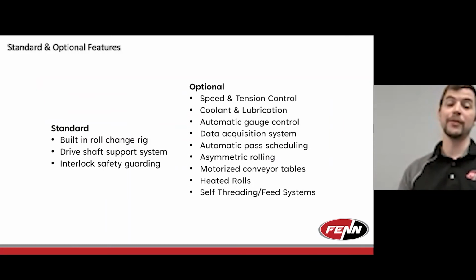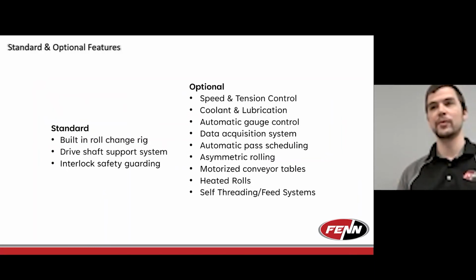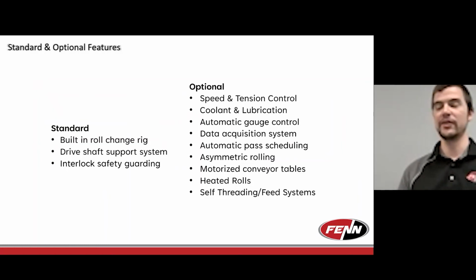So the majority of the time you're doing maintenance on the mills is taking the rolls out to work on them or taking them out to have access to the internals of the mill. So we deliberately designed any modern system nowadays with a built-in rig and a drive shaft support system, with those purposes being to make it as easy as possible to get the rolls in and out of the housings, both in terms of just naturally getting them out, and with the drive shaft support, locking the orientation of the drive shafts in their position so you can easily drive the rolls back in without having to fight the alignment of the drive shafts. So those are just standard features in general that we provide with the mill.